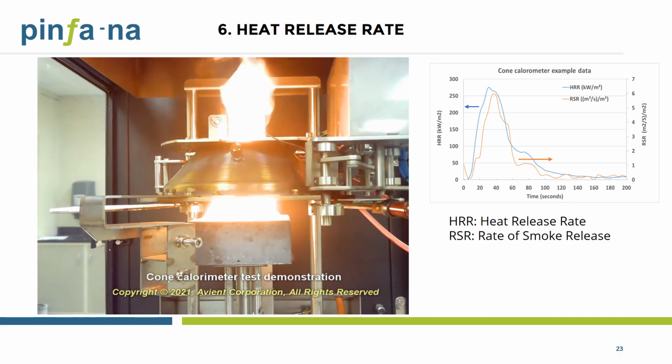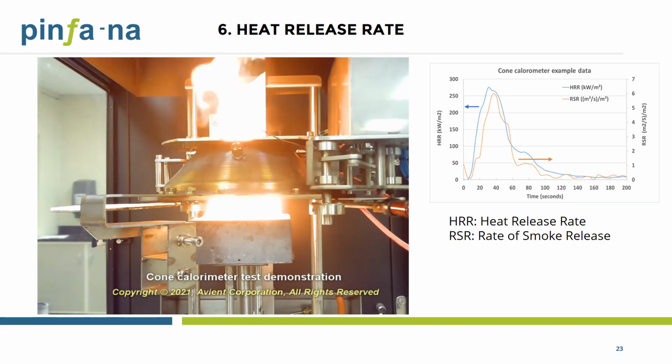The example result of the heat release profile and the smoke release profile of this sample as a function of time is shown on the right. In this case, a major peak with a couple of smaller, shorter peaks are seen in the heat release profile. The smoke release rate curve follows a similar trend.